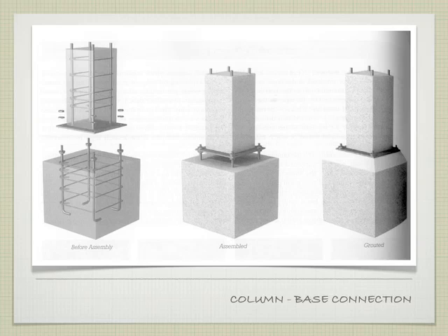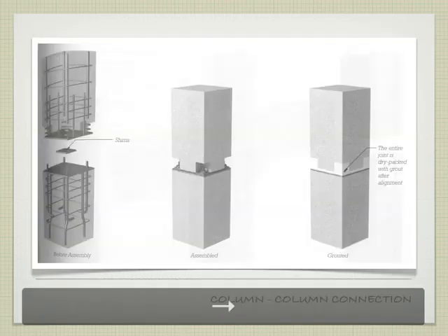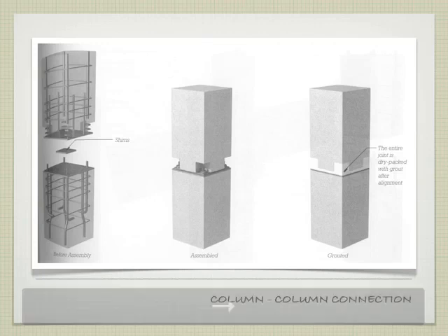The nice thing about this is we have the ability to add shims, add a few extra washers on one side and get that perfectly plumb. Because the bolts, when they're cast in the concrete, as much as we try to make them absolutely perfect, they're usually not. And so this gives us some flexibility to adjust for our overall plumb in this particular case. After we've done that and we've bolted it into place, then we're going to put that grout to cover up as much of the metal connection as we can. Protects it from weather, protects it from rust and that sort of thing.